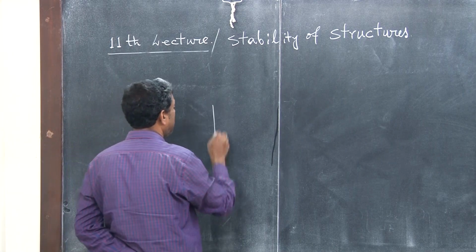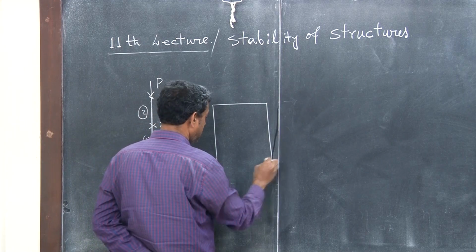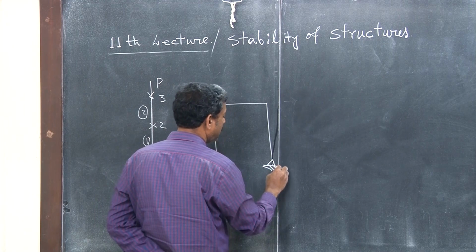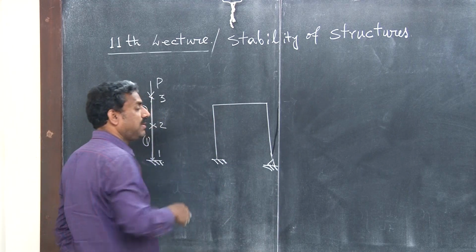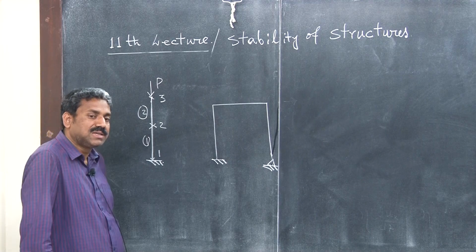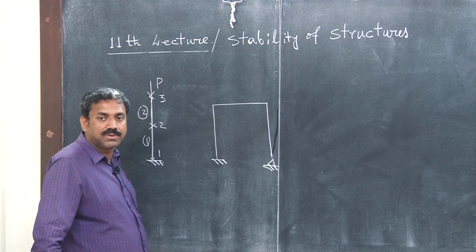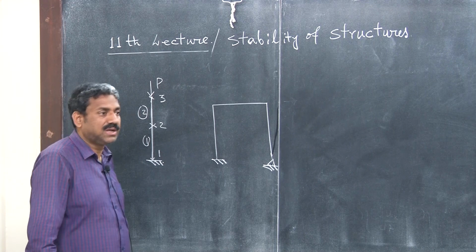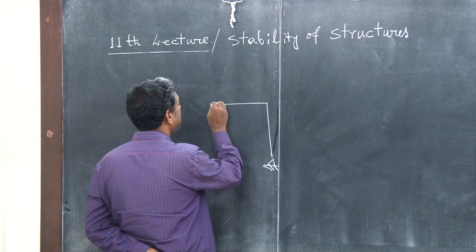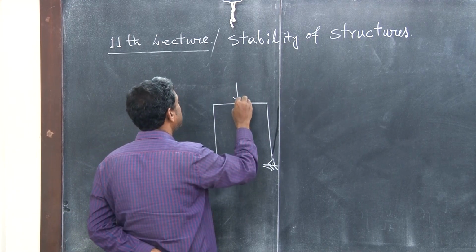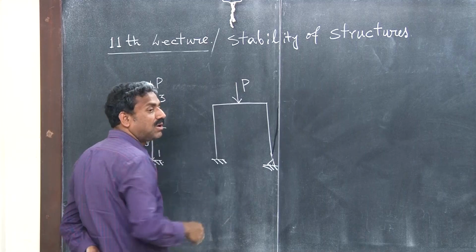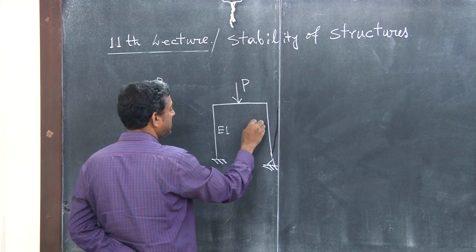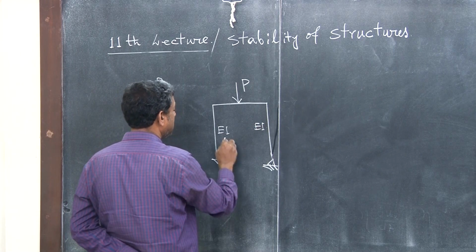Now same thing, this is more important for frame structures, because although for a beam column it is easy, and for plate and shell we also derive the governing equation, for the frame it is difficult to have one single differential equation, right. So it is most handy for the frame. So for example, it is subjected to some critical load P. You want to find what is the value of P so that these two columns buckle, this is length L and length L.